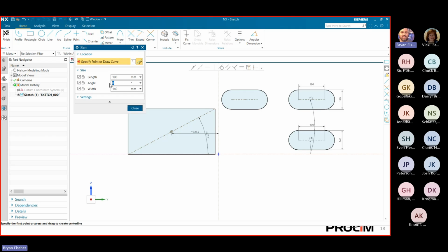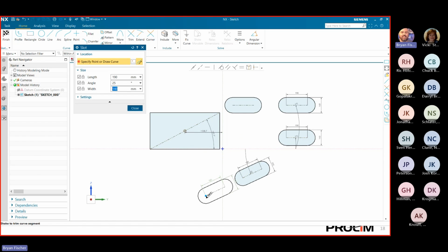a sketch. If you put an angle in it, it will lock it in that angle. So I can create as many sketches as I want in that angle. And notice another nice little thing here: I'm not holding anything here. All I'm doing is coming in, I get a lock on it, and now they're in the same line. It locks onto these other particular parts and allows me to line them up easier. So if I wanted to lock this onto this, I could. If I wanted to lock it on that.